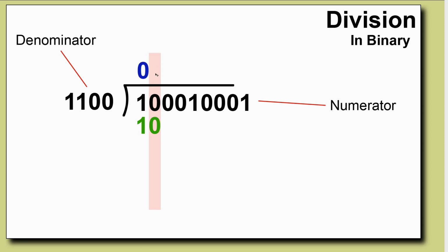So we're only ever going to divide 1 in. So we can actually talk about this in different terms. We're no longer describing this as a divide. This is simply a comparison to see if this number is greater or equal to this number. And comparing two numbers and performing a subtraction are things we've already got operations in the ALU to do. And so immediately looking at this operation in binary, we're looking much closer to the kind of things that we can feed through the ALU on the CPU.